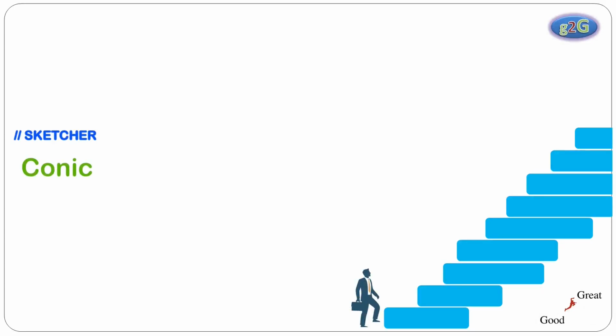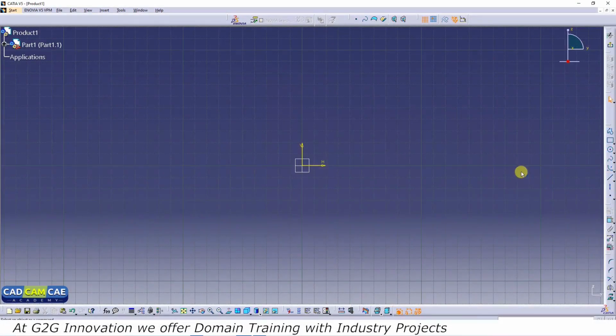So guys, let's see the last feature in Conic. So let's click on the command. It is named Conic. Let's see how we can draw a geometry using this feature. In order to create a geometry which is similar to a parabola or hyperbola using this Conic, we need to define 4 points. And all the 4 points will define the boundaries of the conic profile.